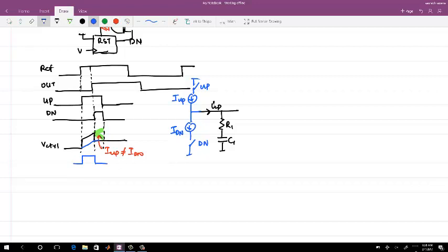For any phase error, phase offset or any delta phi, we start having this every reference period, right? This can be delta ICP, the difference between the ICPs, this jump can be due to the difference in the current, even in a locked state. It can be due to a certain phase offset, but this is going to happen in the PLL at every reference period.